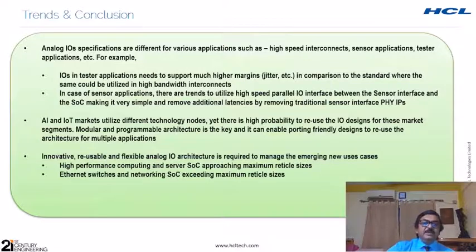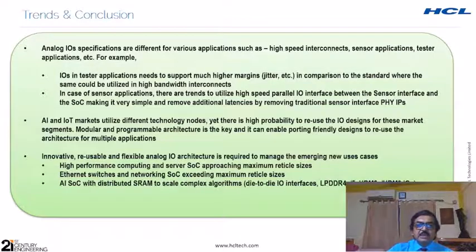And in different use cases, like in high performance computing and server ASICs, server SoCs that are approaching maximum reticle size, the Ethernet switches and networking SoCs that are also approaching maximum reticle size. And then there are these AI SoCs that have distributed memories to support complex algorithms, and they require die-to-die I/O interfaces.